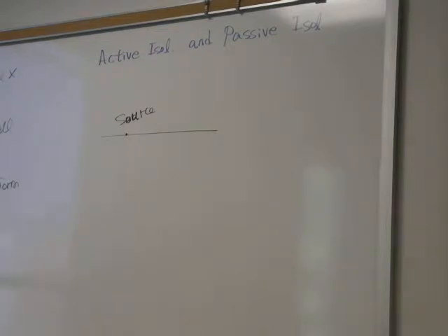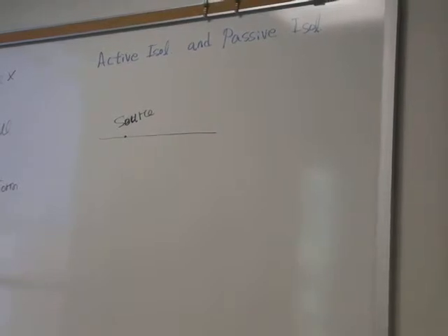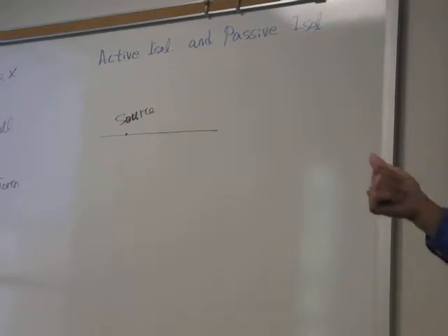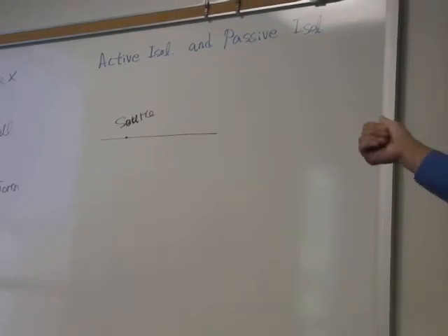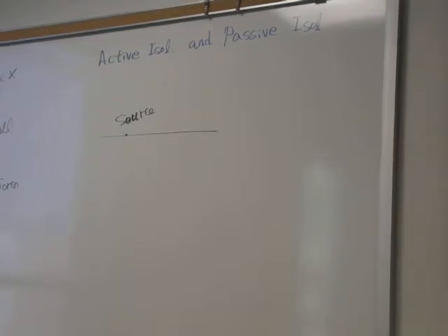Nowadays, isolation of those vibrations to the structure itself or machine itself is also well developed. As far as you can effectively isolate your structures using rubber pad or whatever, that is actually more economic than designing and building those trenches or whatever.